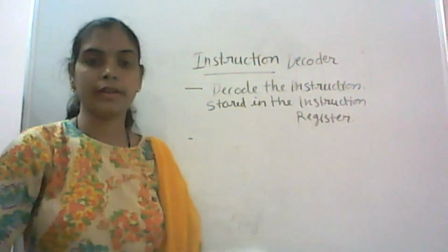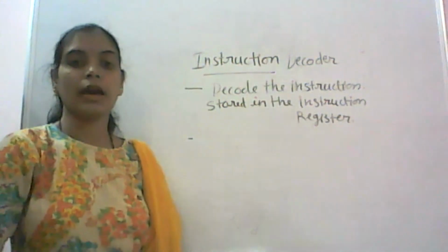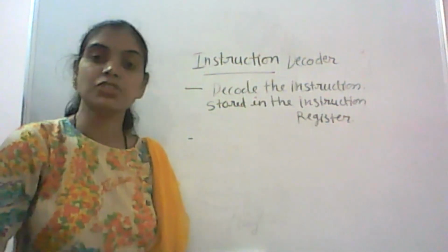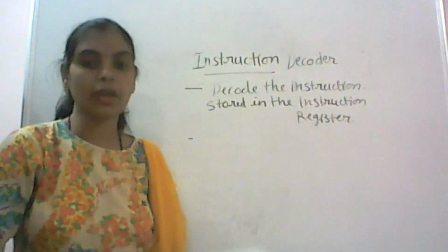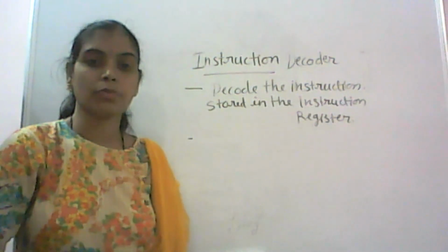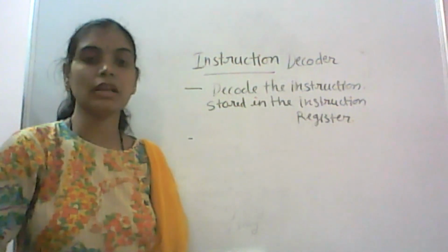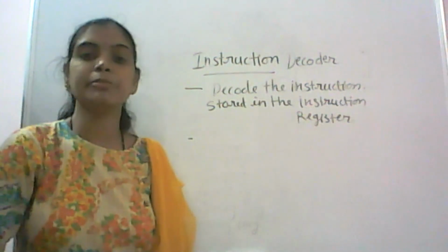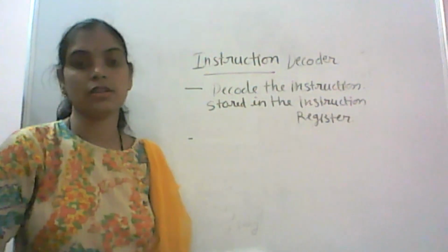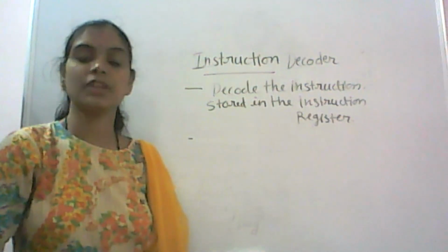Okay, you can take a screenshot of this block diagram and see in this block diagram accumulator, status, B register, B, C, D, E, H, and these are the general purpose registers. Okay, after that stack pointer, program counter. Now you see the general purpose register. There are 6 8-bit general purpose registers, namely B, C, D, E, H, L registers. Okay, B, C, D, E, and H, L.